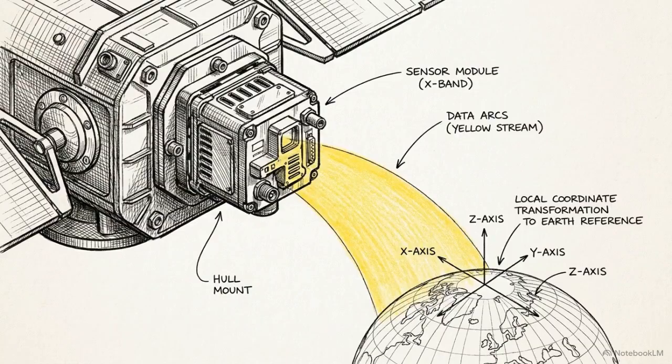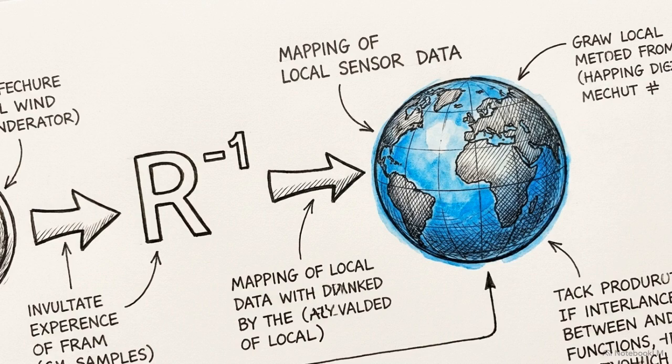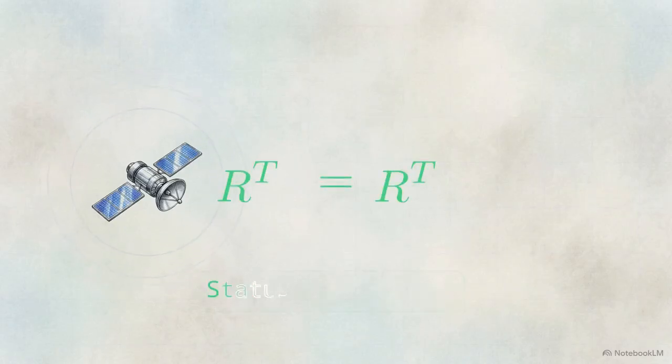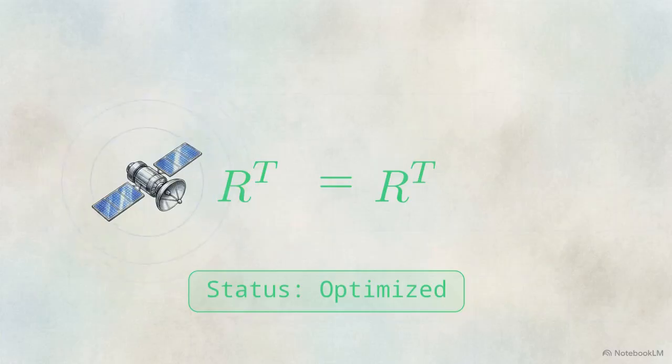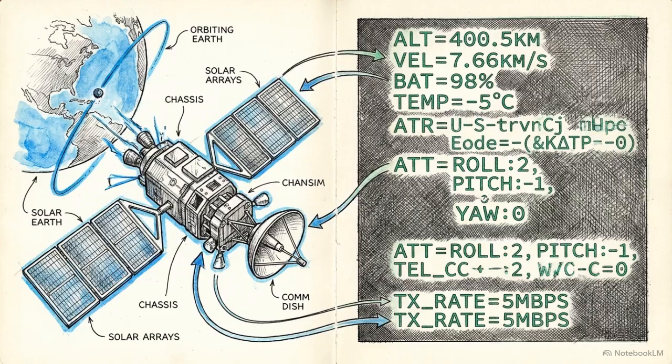When flight software needs to reverse a coordinate transformation, mapping local sensor data from the body frame back to the global frame, it calculates the exact inverse of that rotation matrix. Because rotation matrices are structurally orthogonal, the inverse is simply equal to the transposed matrix, providing a highly efficient computational shortcut for real-time flight software. In attitude kinematics, the determinant enforces strict physical reality, while mathematical inversion translates telemetry bidirectionally, without losing data.